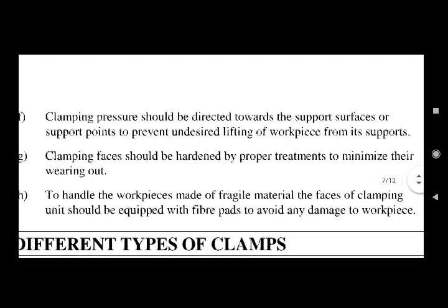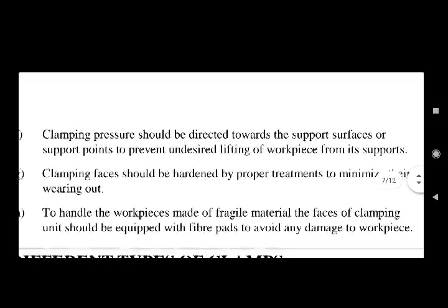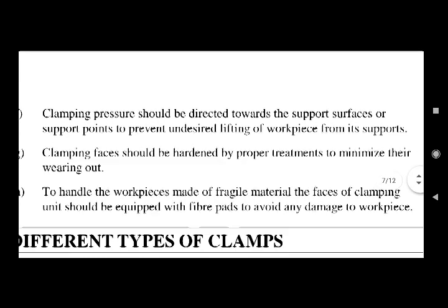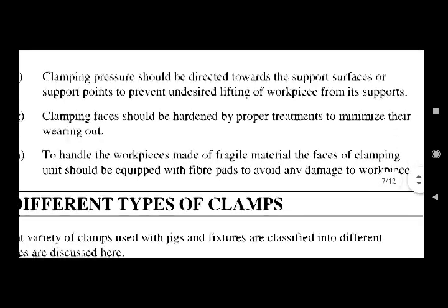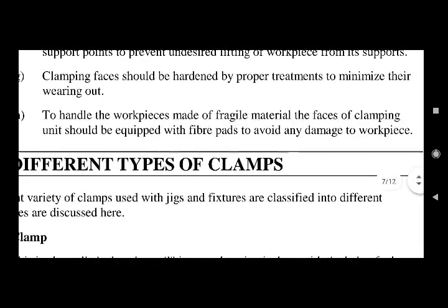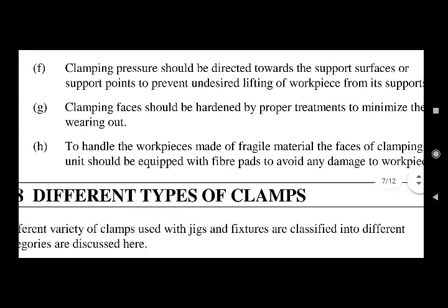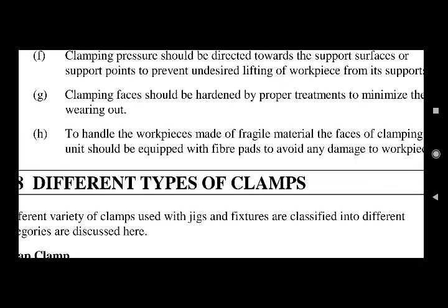Then, clamping pressure should be directed towards the support surfaces or support points to prevent undesired lifting of the workpiece from its supports. Clamping faces should be hardened by proper treatments to minimize their wearing out. To handle a workpiece made of fragile material, the faces of the clamping unit should be equipped with fiber pads to avoid any damage to the workpiece. So, these were the requirements associated with the clamping process.